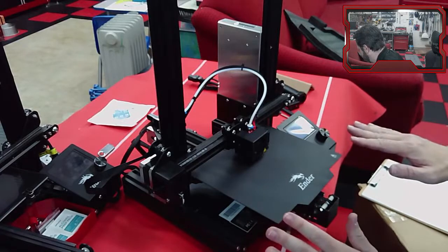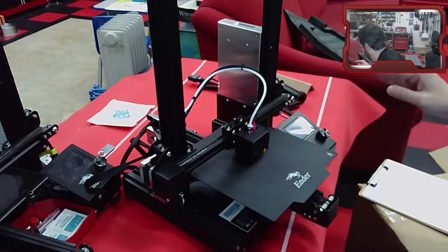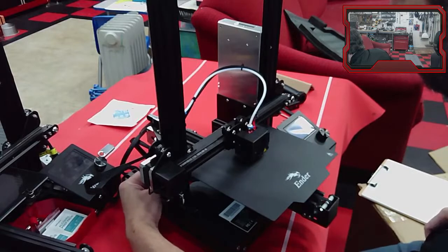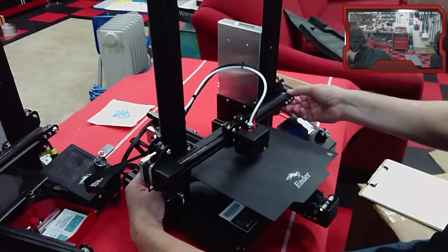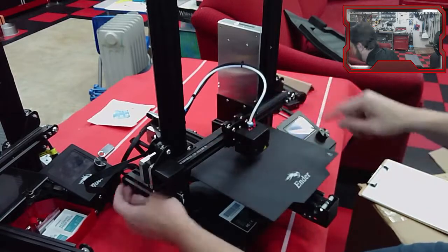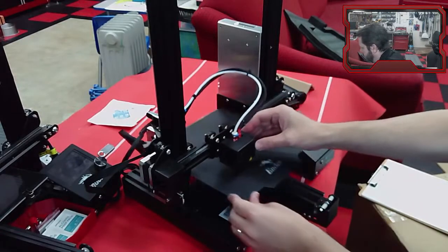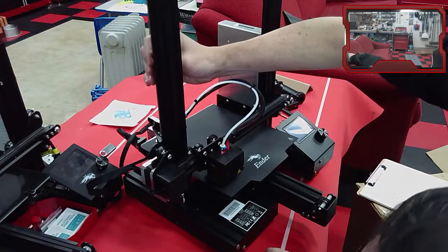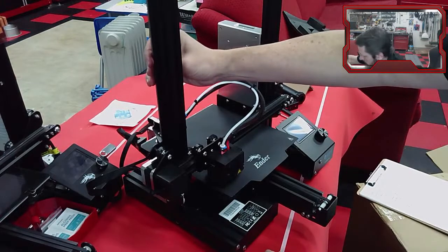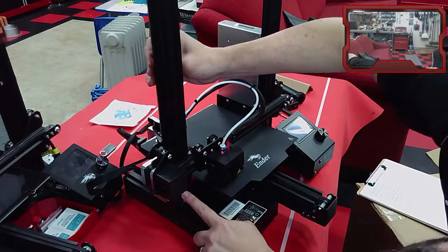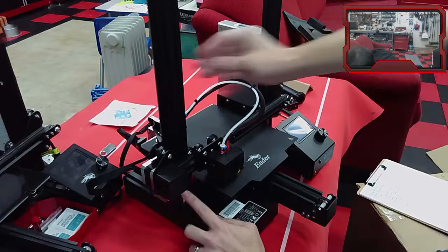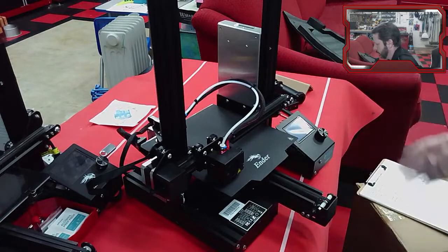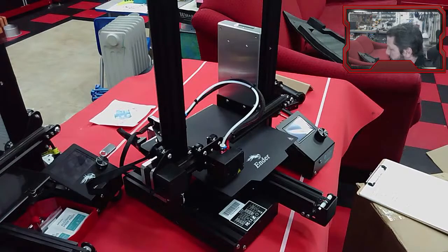So what you would do next is power it on, for one thing. We still have to worry about this Z movement. It's still not the way it should be because we're really sloppy over here. So we're going to have to work on those adjustments. You want to level your bed. So basically you put it in the 4 corners and you can kind of hear that's the Z endstop triggering. So it looks like I'm going to need to raise the Z endstop a tiny bit. So now it's all of the little pieces of getting everything level and moving right. I'll save that for Tuesday.